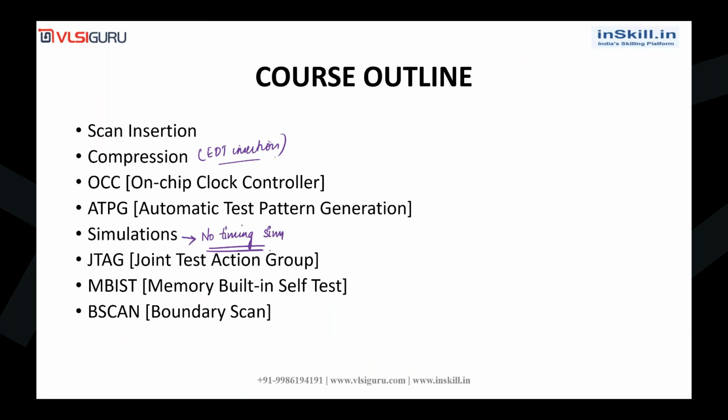The reason is that in order to do timing simulation, we require a file called the SDF file, standard delay format, which is not available in the test cases at our institute.